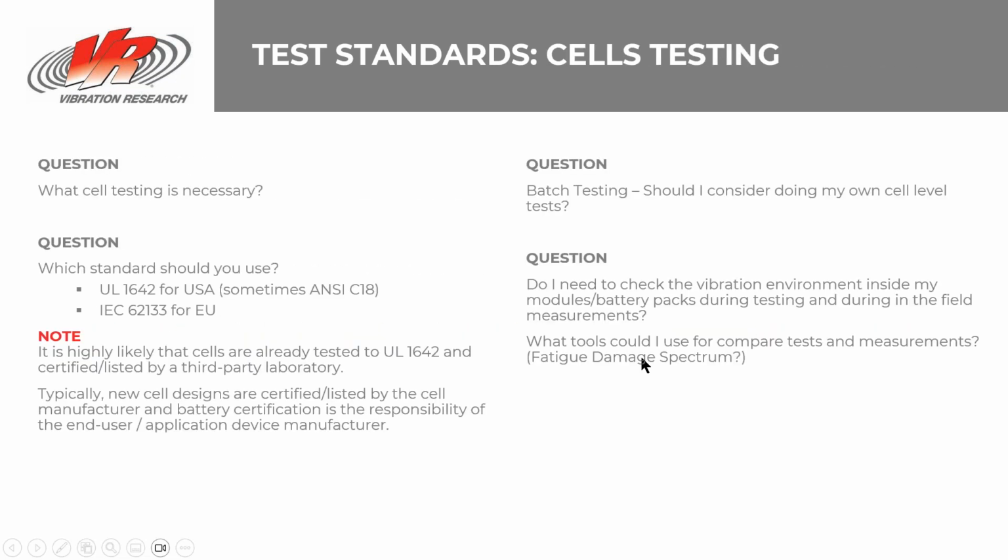The other thing there at the bottom is, if you are having cell vibration tests done to a standard, it might also be useful to compare the tests the cells are being done with against the actual field environment. So you might like to use fatigue damage spectrum for that.